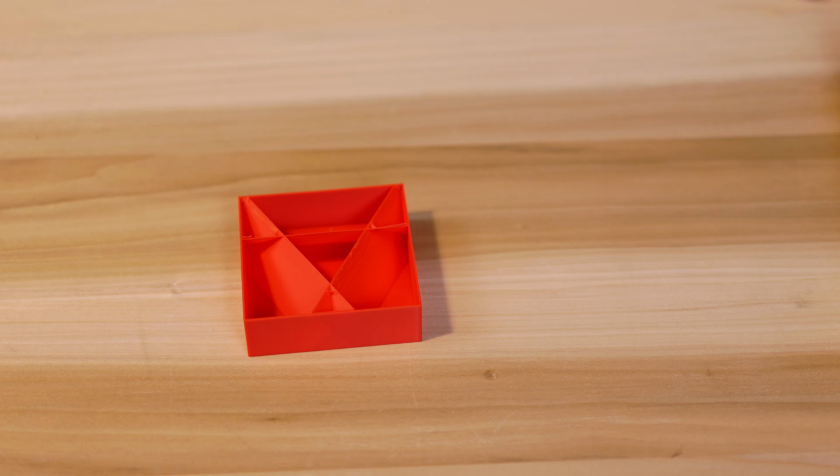Support cubic is the next one, and that is a cubic pattern optimized for support structures. Use case is parts with overhangs or complex geometries. A pro for this type of infill pattern is it provides optimal support with efficient material usage. Con is it's specific to support structures only. Printing tip, adjust the support density for best results. For the cube, it took 45 minutes and 43.83 grams of material.